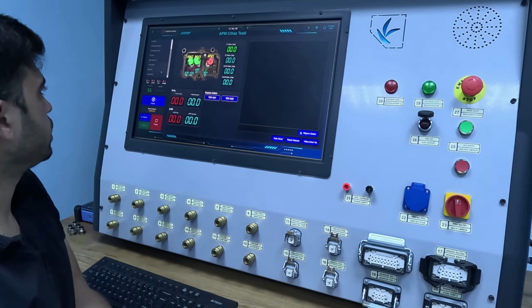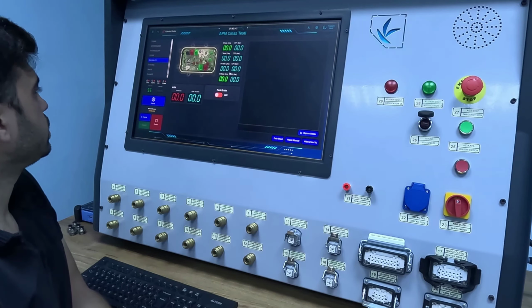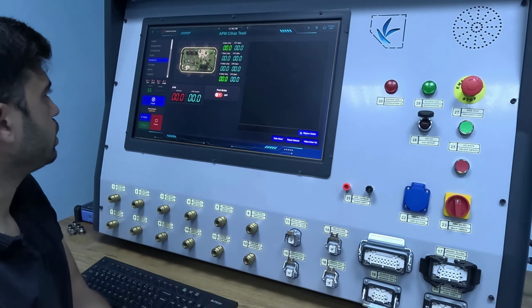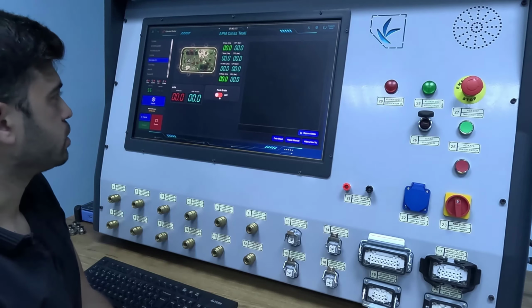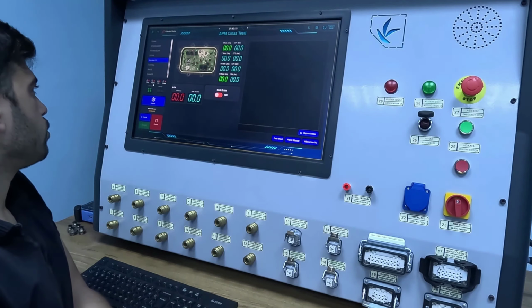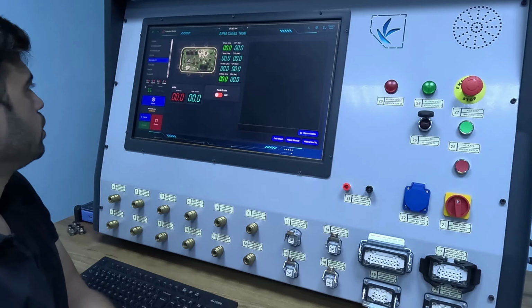There are many APM options readily available here. Many options are available, including Mercedes, Ford, Scania, and more brands. For example, with the Mercedes APM, you can quite easily see information like inlet pressure, outlet voltages, and temperature by connecting manually to it. Right, depending on the APM, some have automotive Ethernet and LIN bus, while others might not. CAN communication might be present.